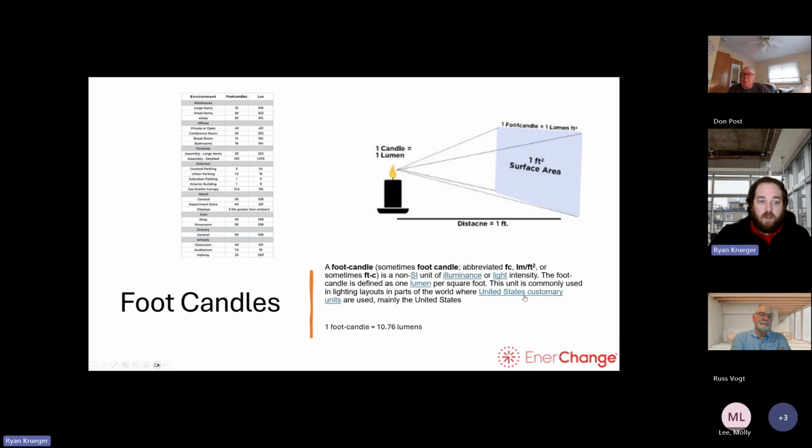But when I'm going through, I have a sensor that allows me to know exactly what the foot candles are. In a lot of applications, you end up in a church sanctuary where they have skylights and you hit it on a Tuesday at 10 a.m. where the sun is completely overhead, and you take your reading and it says 75, but you know that is not actually what it is. So it's just a game of getting my initial numbers and knowing where I'm gonna need to do some magic, I guess.